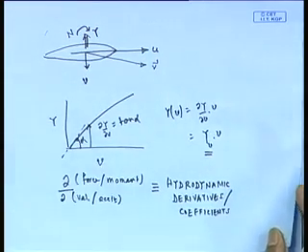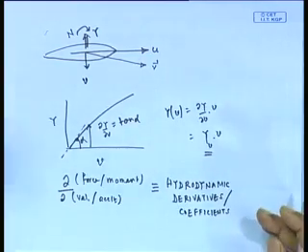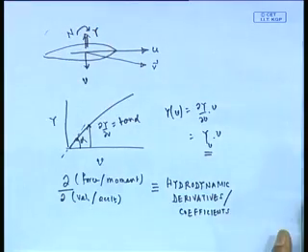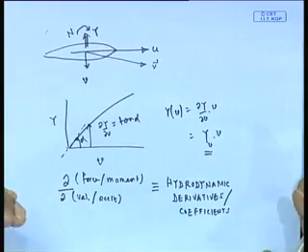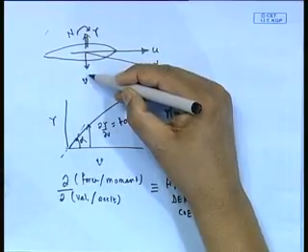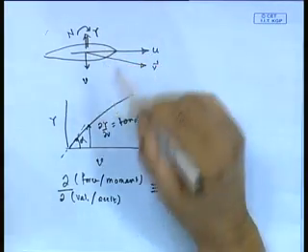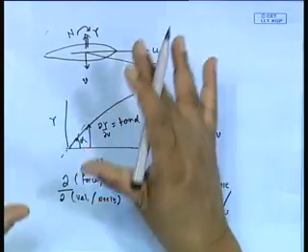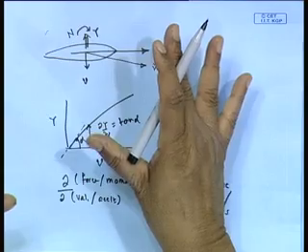This is a very important concept. I have a given geometry. Now, I am trying to give it some kind of acceleration in some direction. I will come to this term by term, and we will see the magnitudes, etc. Then obviously a certain hydrodynamic force is created, which will depend on the geometry. Suppose you take a ship with a particular geometry. If I give a v, regardless of whether it is today, tomorrow, or the day after, it will give so much Y. So, dY by dv becomes an intrinsic property of the hull, the characteristic of the hull.